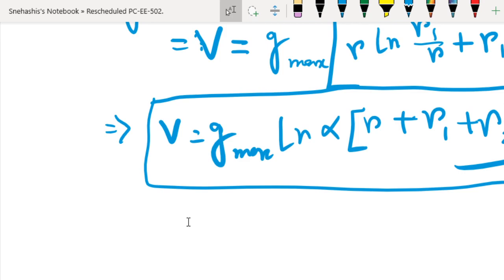The second reason is that with time the permittivities of the materials may change, as a result of which the potential gradient distribution may completely change and may even lead to complete rupture of the cable dielectric material, even at normal voltages, due to aging mainly. You know that due to aging properties degrade, so permittivity also degrades. Today you are using one cable at some certain voltage, say 132 kV. After 10 years, that 132 kV may cause damage to your cable.